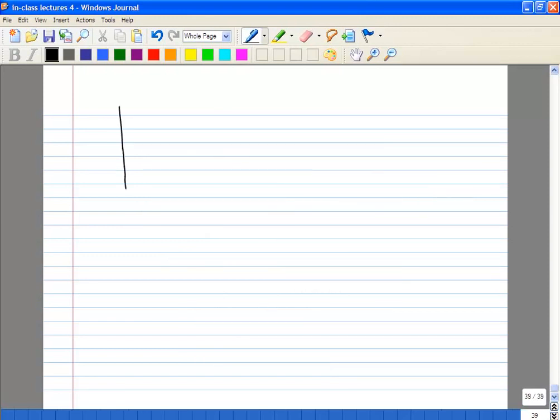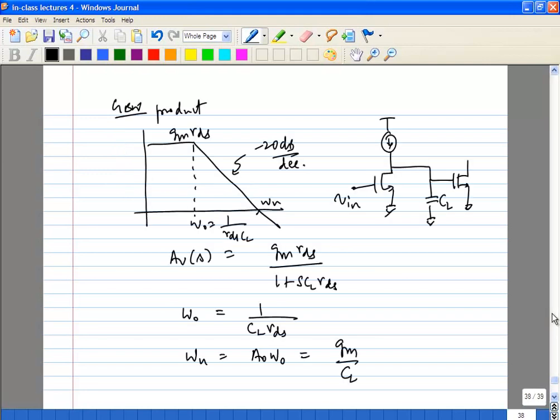Now, if you want to design a second amp, what you know is, given the amplifier itself, you can operate at multiple points. For example, you can operate on this curve. You can operate at a lower gain and a wider bandwidth. So that is your gain bandwidth trade-off, right? Now, suppose you want to increase the bandwidth further. What can you do? Assume your load capacitance is fixed.